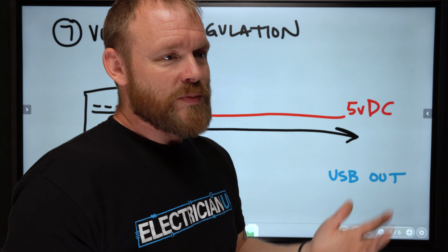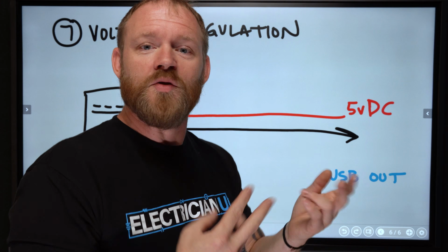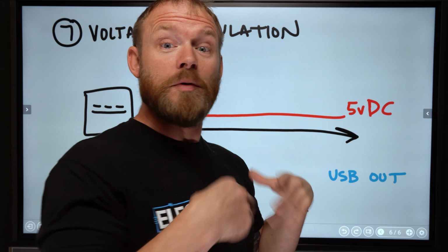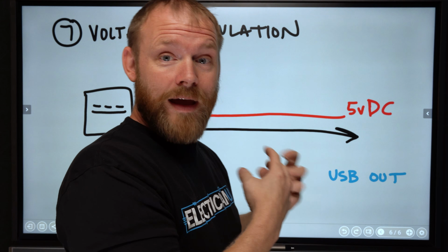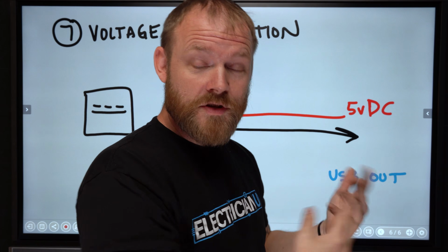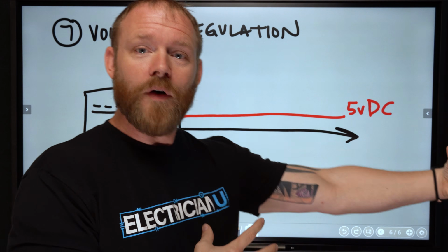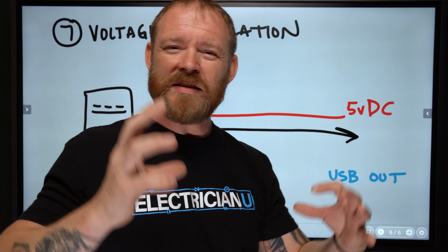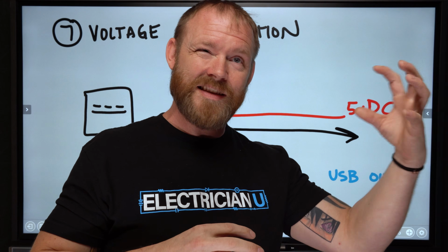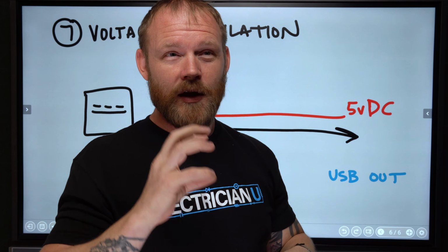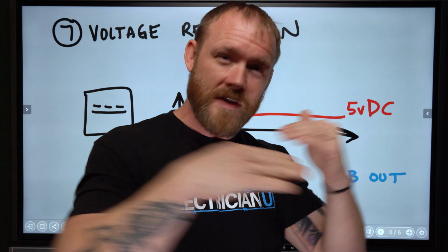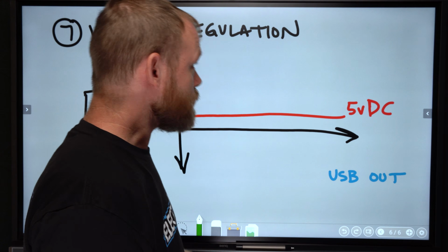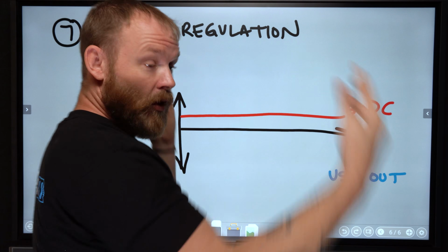Now, typically with a USB, there's going to be 2 signaling wires that can go back and forth, positive, negative, and then there's going to be power, where you can send actual 5 volts of power to something to charge it. But a lot of the devices and the chargers are able to talk back and forth to each other, and they can kind of self-regulate to figure out, well, that's this kind of device with this kind of charger, so we want to make sure we only have this much current going in to charge it, otherwise they would destroy devices. But that's essentially the whole thing.